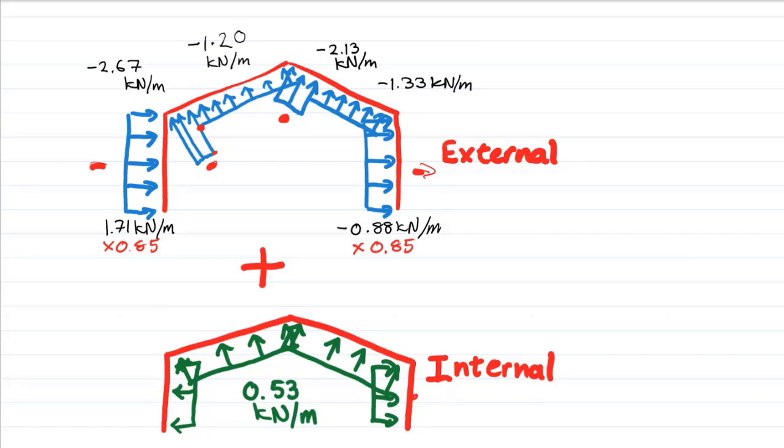It depends on your analysis and how many cases you're doing, whatever's easiest. Either would get you to the same answer. Normally the software will just convert those distributed loads to point loads at each node of your model. Otherwise you could do that yourself, just multiplying the UDLs by the distance between each node you are working with.